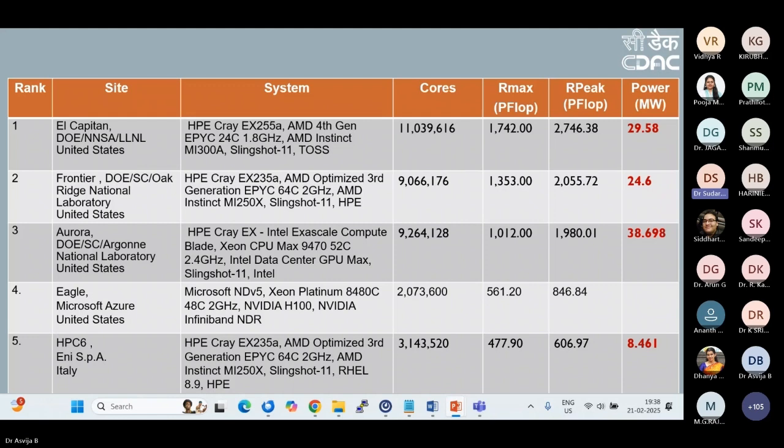What kind of memory is being used? What is the distance between the memory and the core CPU? How well is the high bandwidth memory connected to the core and the CPUs? How does inter-core, inter-chip, and inter-socket communication happen, and what is the energy consumption for it? And what are the voltage rails that we are looking at? So suddenly it is no more just software programming for HPC, but something where you are actually situation aware of the entire ecosystem. So the optimization has to be global from an energy consumption perspective.